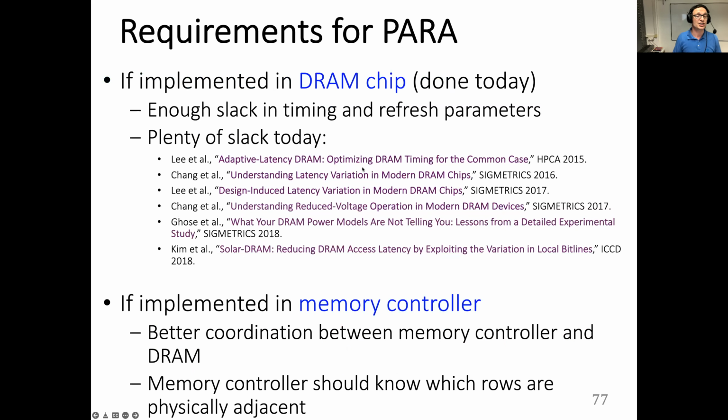Actually, a lot of manufacturers use variants of our solution internally because we reverse engineered a lot of the solutions, as I will discuss later. You need some slack in the memory timing and refresh parameters, and manufacturers are using that slack today. In DDR5, there's the RFM command, which actually increases the slack a little bit by putting more burden on the